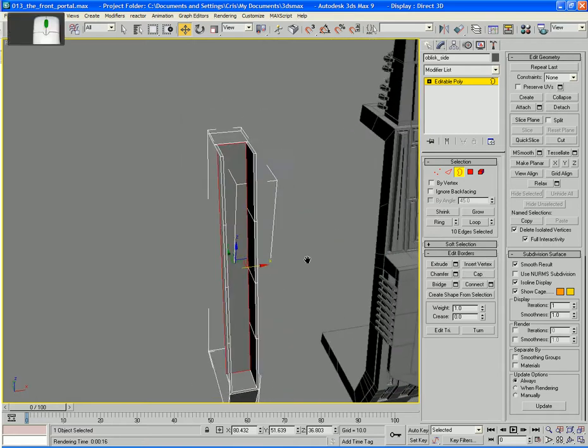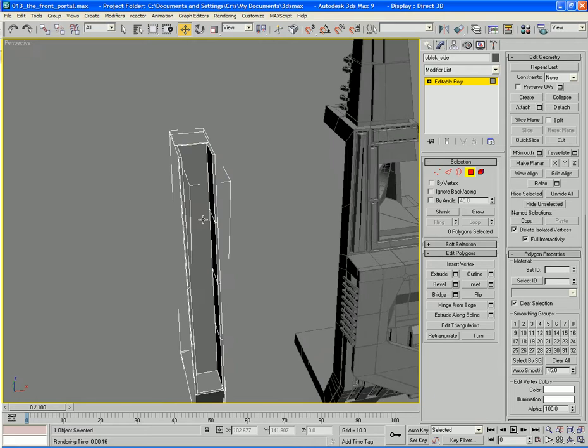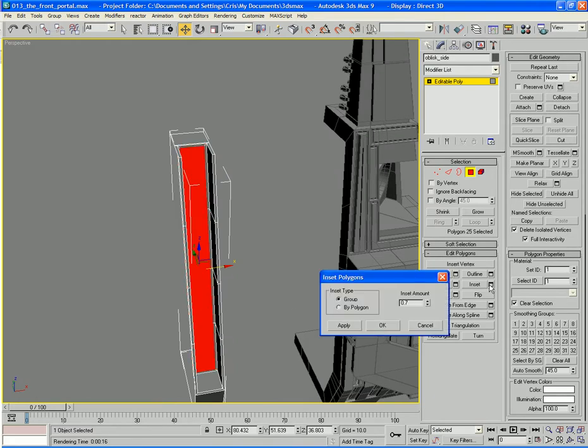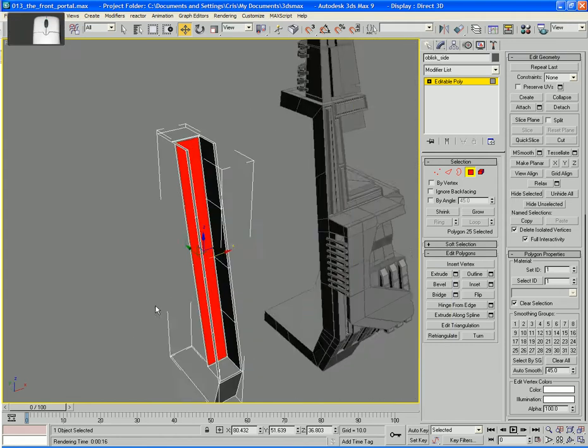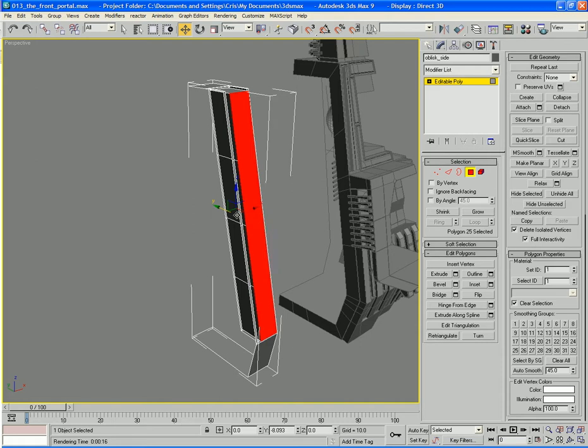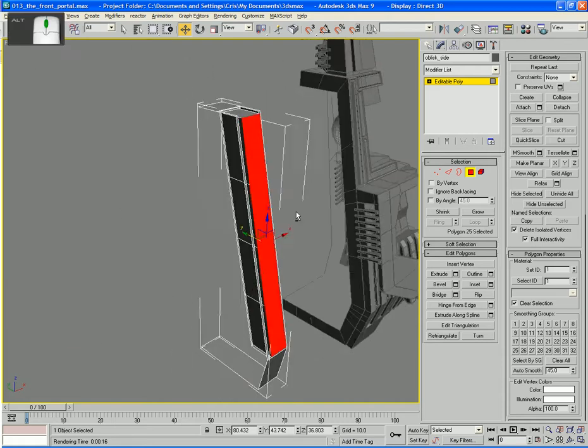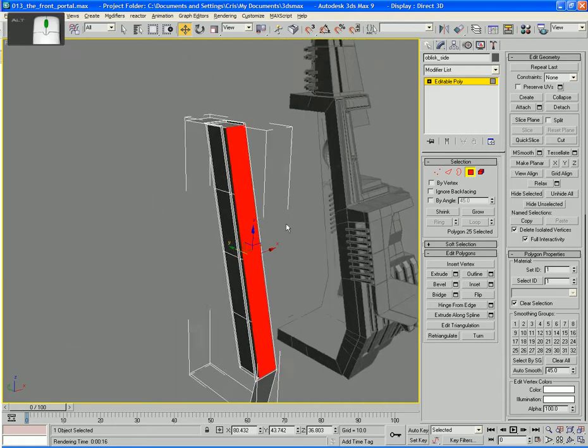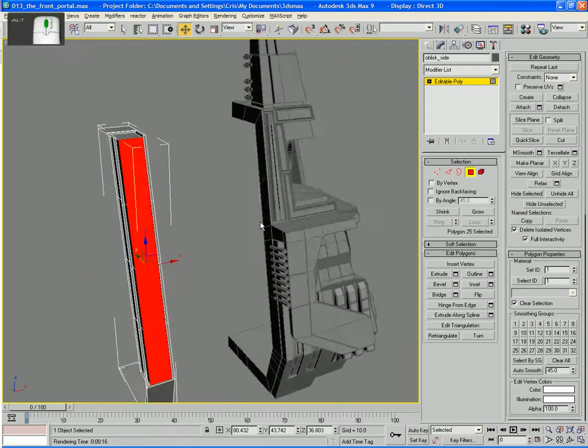And I don't need to worry too much about joining up the lines in the middle by doing cuts, because what I'm going to do is an inset, which will deal with some of my problems anyway, make that about 0.45, and then I'm going to extrude it by group 0, and I can now bring this forward to about there. And this is going to give us room to do our cunning designs and refine this and make a good shape from it.